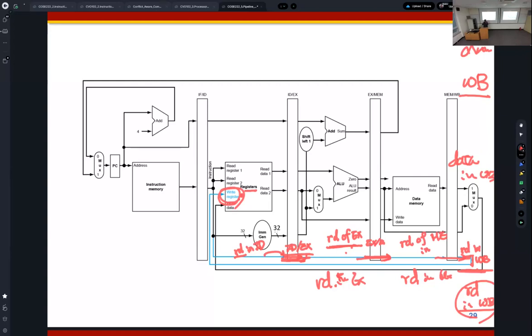Okay. So when a certain data is given to the data path element in the pipeline architecture, we need to consider the timing. We need to use the correct timing of the data. It's very important. Sometimes students can be confused because, oh, RD, we need to access the register file, so RD is just connected from this pipeline register.